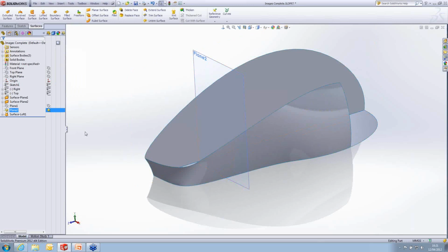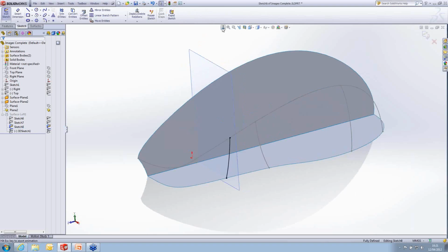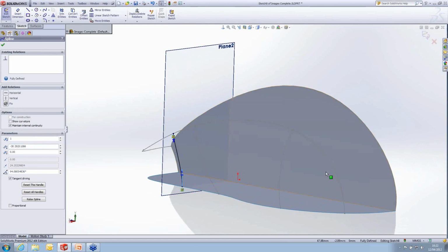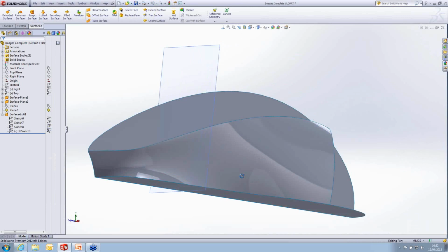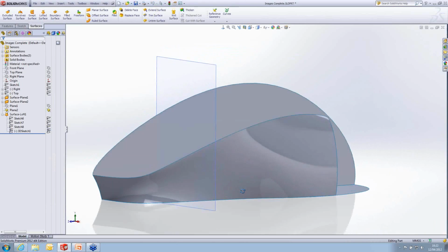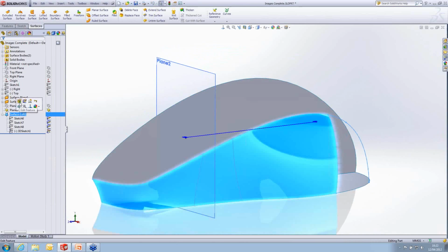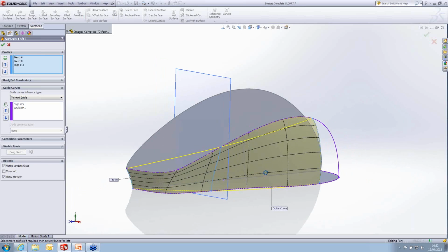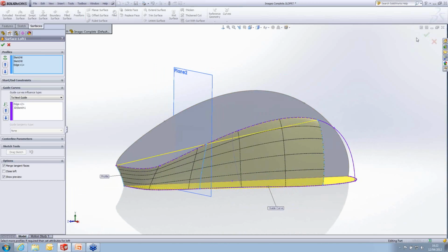Okay, so adding in this new sketch now, it leaves me with a new profile that I can use in this loft. So I'll just edit the sketch for that, and then I can slightly adjust the profile a little bit to make it undercut a little bit more. And we can see the profile matches a bit more nicely. So I'll just edit that loft and we can have a look at it. Okay, so that's the loft profile as it moves along.